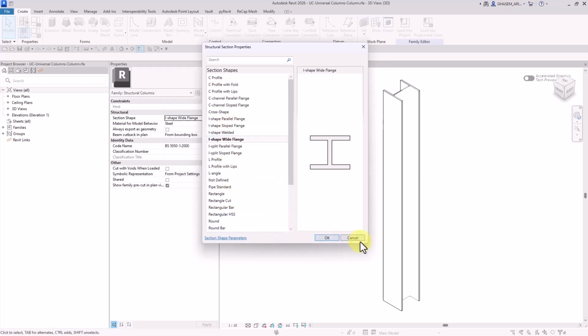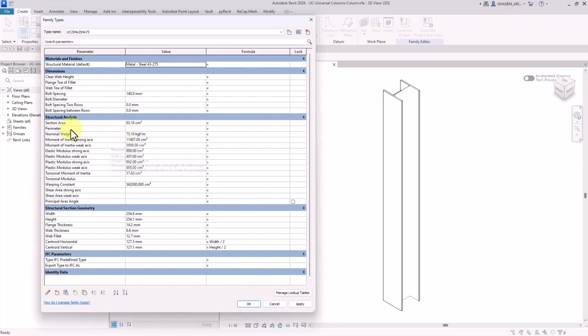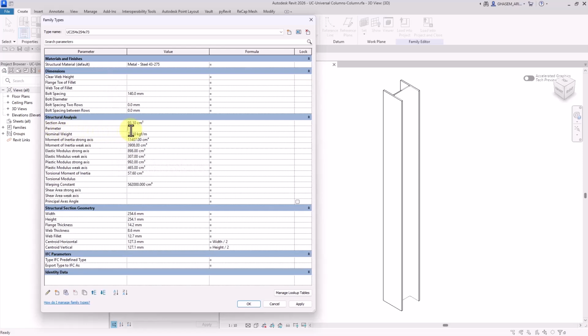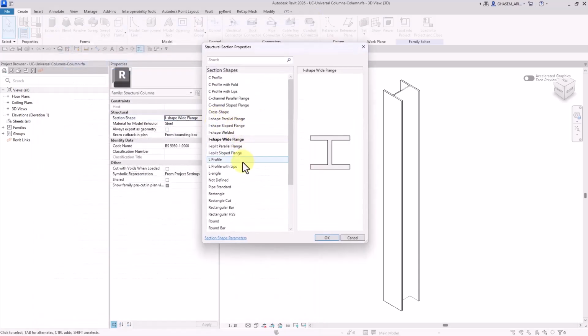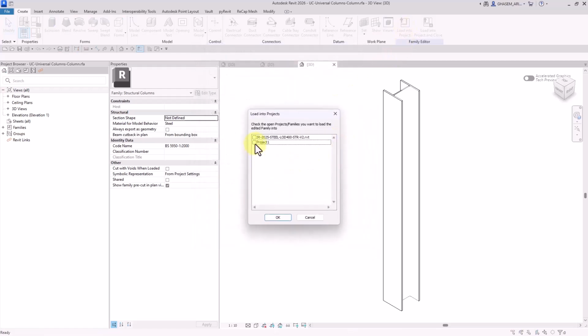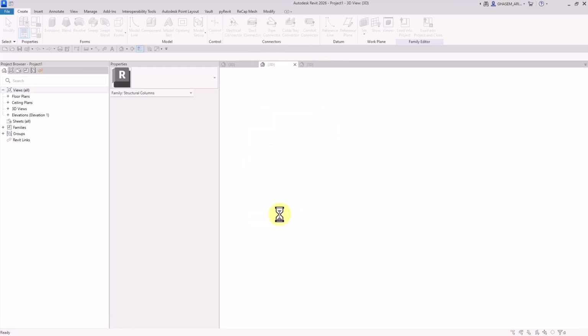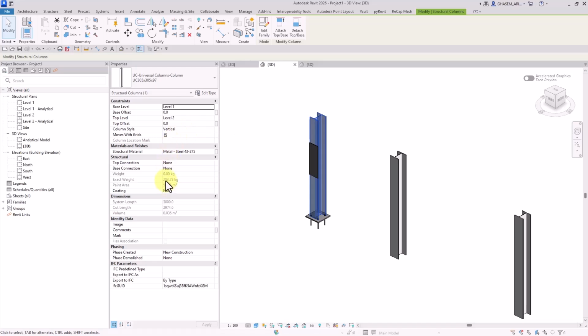Now, again, for the 1000th time, guys, paint area would be calculated through multiplying perimeter by the cut length. The thing is, the software won't really recognize this parameter by default. We need to specify it manually ourselves. Funny thing is, if we set this on not defined, guys, this problem would also be solved. You know, this is somehow a problem, but it also is a loophole, in fact. I mean, it should work based on the section shape. But anyway, now as you can see, both of these parameters are calculated.